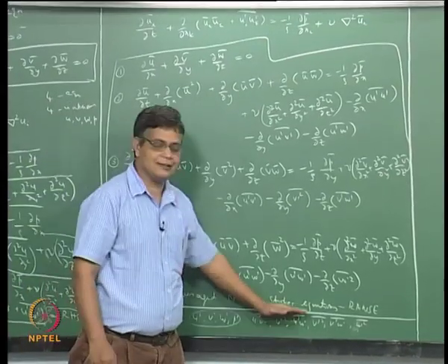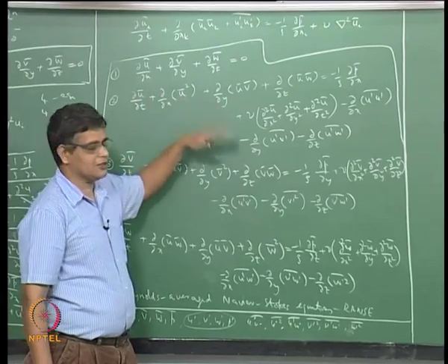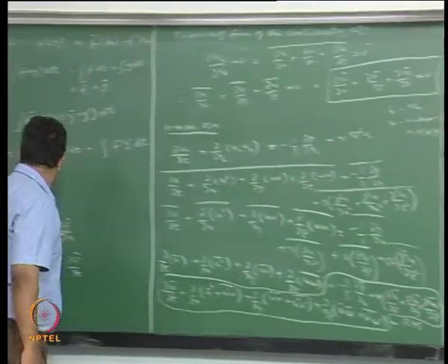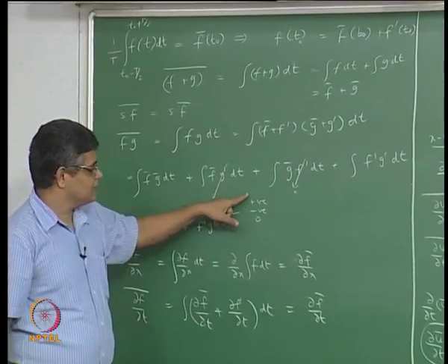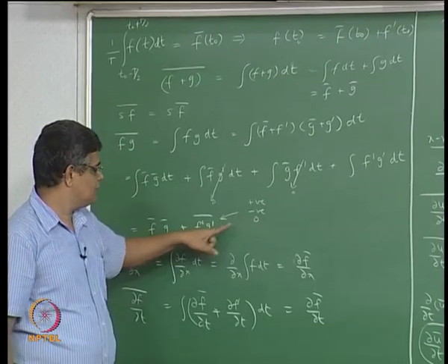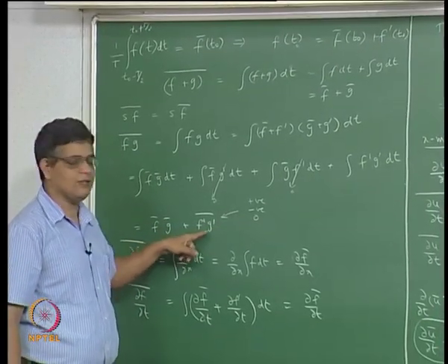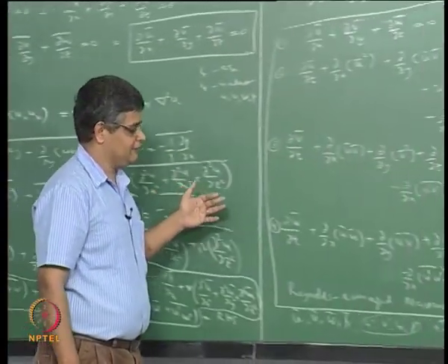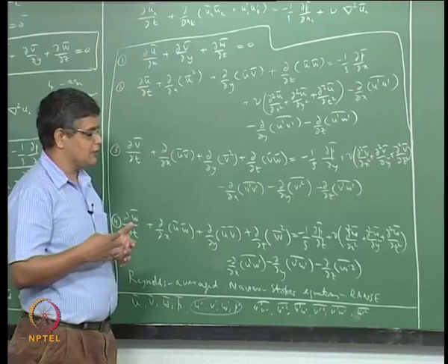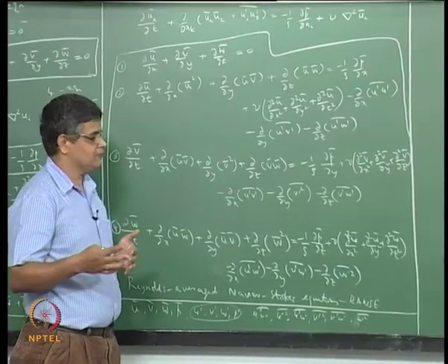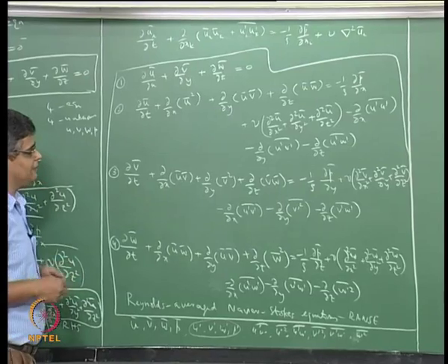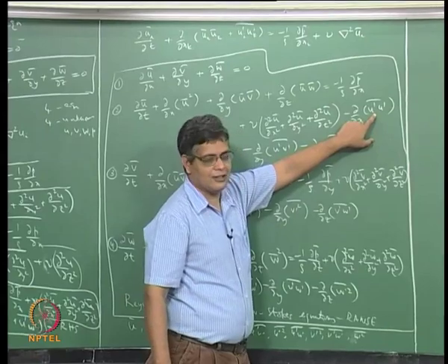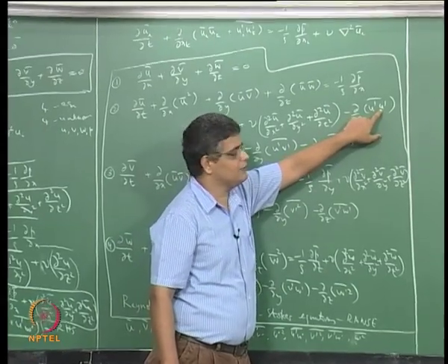If we say we neglect these things, then we are leaving out those terms, and are they 0? We have said that f prime g prime bar here may be positive or negative or 0, and it is only 0 if the fluctuations in f and g are not related. At this stage, can we say whether these are related or not related? Even if we were to say that the fluctuations of u prime, v prime and w prime are not related, independent, even then we would still have this quantity here which is non-zero, because it is a u prime square.